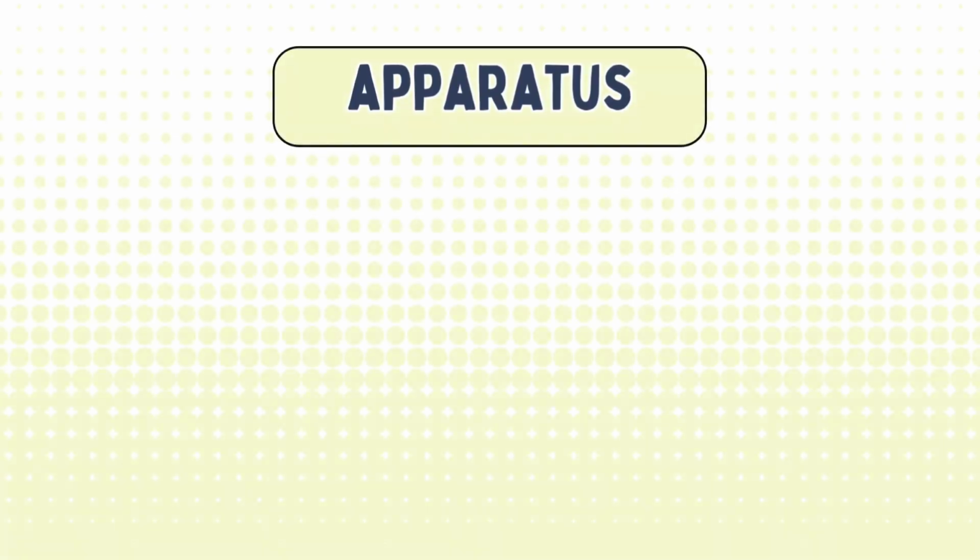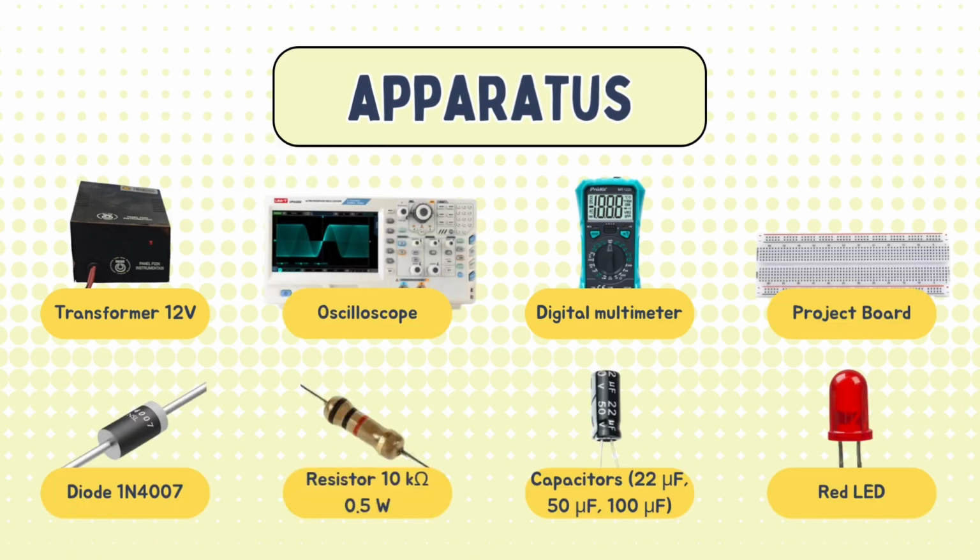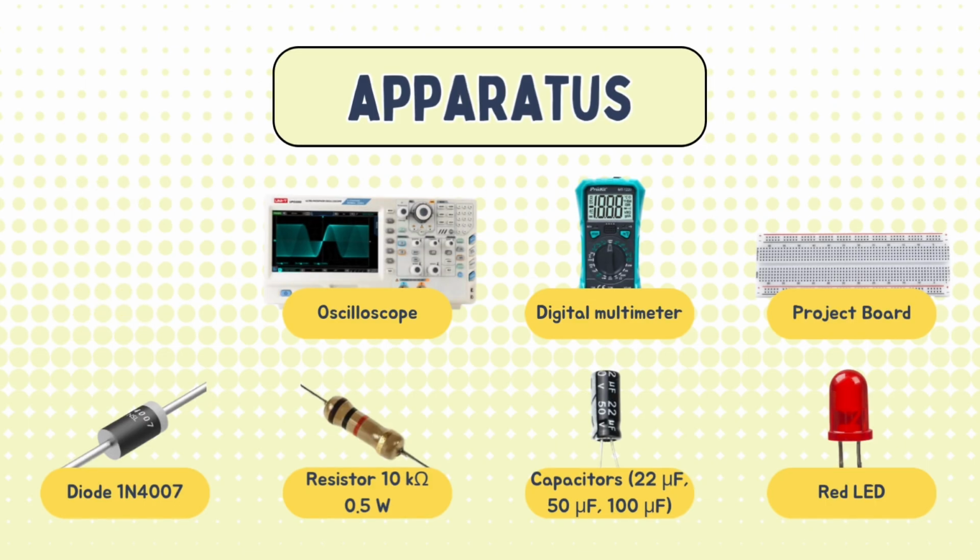This experiment was done using a transformer 12V, oscilloscope, digital multimeter, project board and connectors, 2 units of diode 1N4007, resistor 10 kΩ 0.5W, capacitors 22 microfarad, 100 microfarad and 50 microfarad and a red LED.